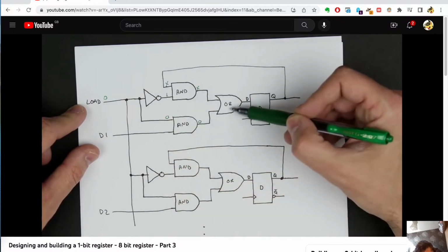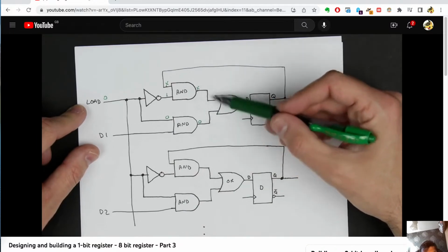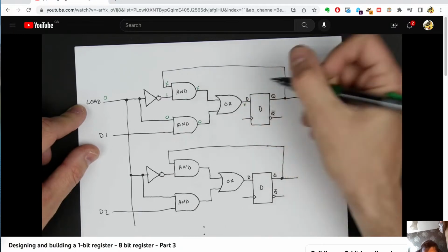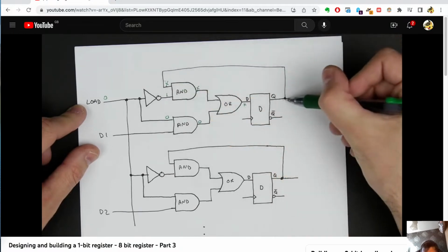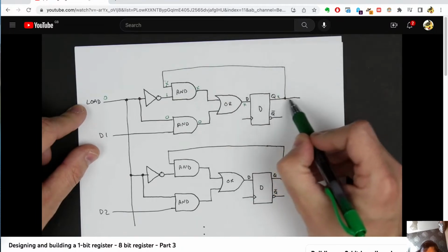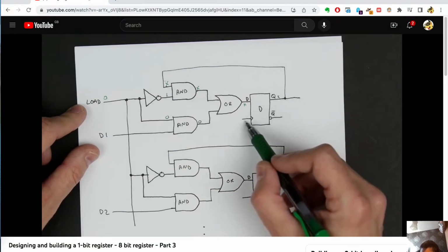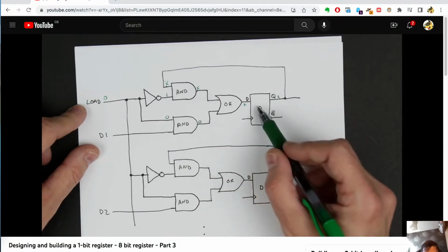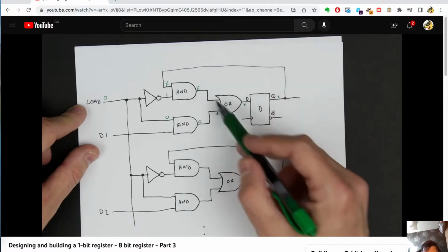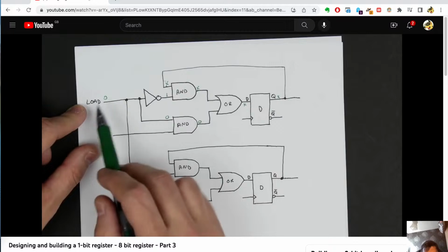So now we have an OR gate here, so we're saying 0 or whatever x is. Well, that's just going to be whatever x is. So x, that's what's being fed out of the D flip-flop, right? So whatever's stored in the flip-flop is just getting put right back in the input. And so whenever this clock transitions from low to high, the D latch essentially just latches in the same value that it has, and nothing changes. And that's because our load is 0.